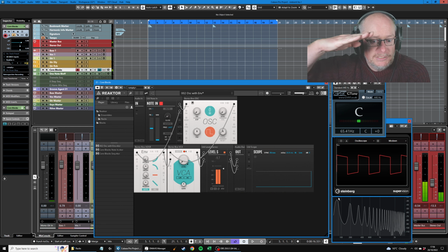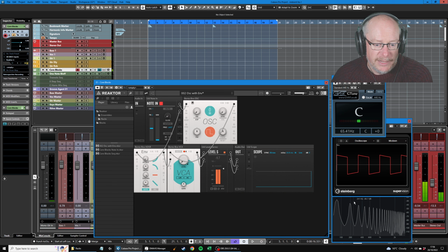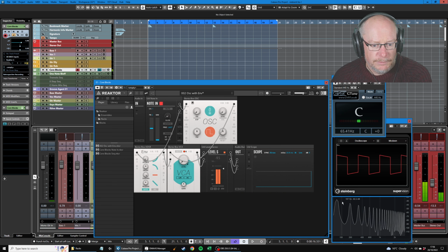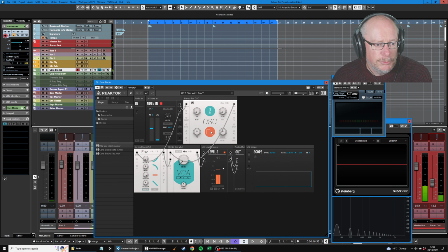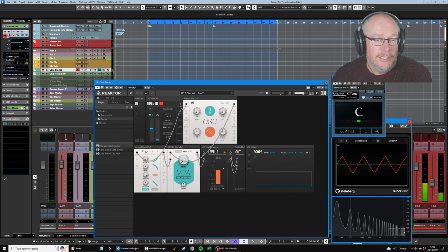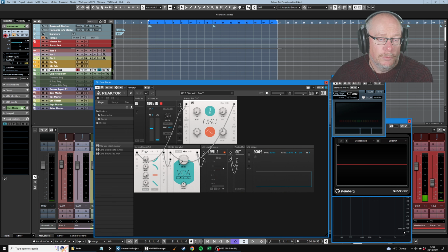Now, if you have a look at the rate of attenuation of this square wave, here they are. If I switch to a triangle wave, you're basically going to get exactly the same number of harmonics, but they're going to tail away faster. So just take a note of that angle. It's maybe 20 degrees. Let's dial up a triangle wave. And now they tail away faster, and you can hear it's a softer tone. It's closer to a sine wave. It's closer to that soft purity of the single harmonic.